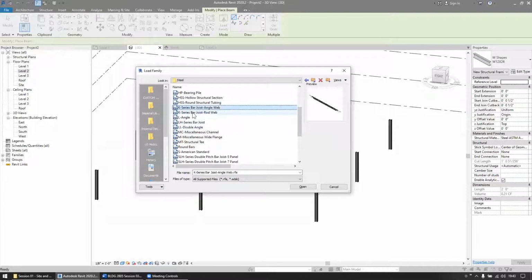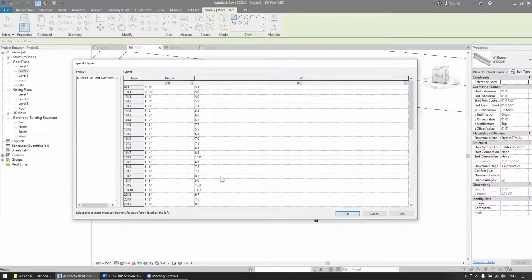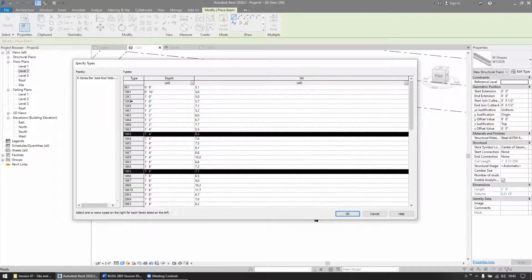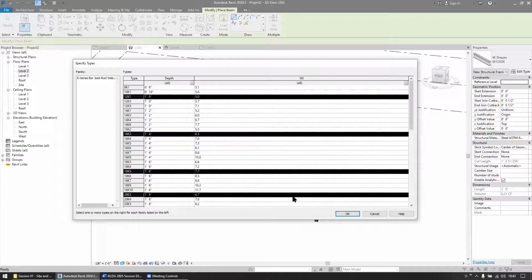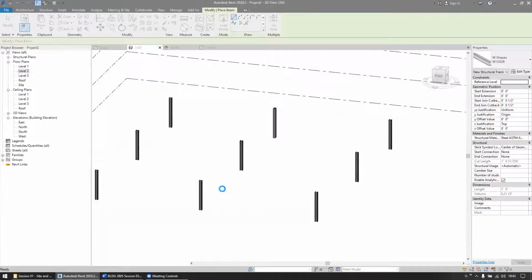Now, with many of these structural engineering objects, when you load them up, Revit has a catalog of different sizes for these objects. So, you know, if I want to grab the 16-inch bar joist and the 18-inch and the 12-inch, you can see I'm holding down the control key to add these into my model. So now all four of those will be loaded into my project.